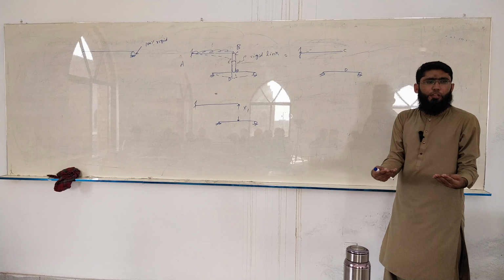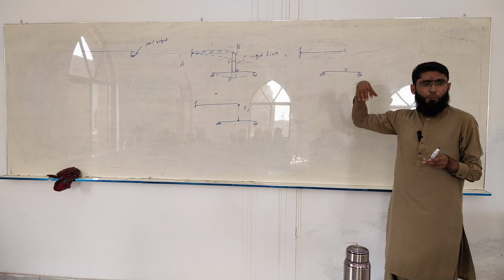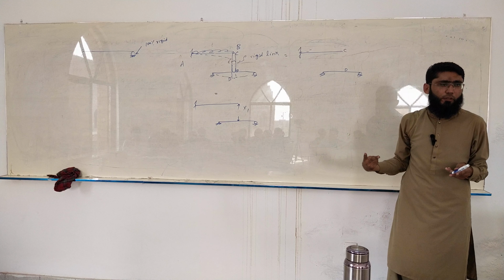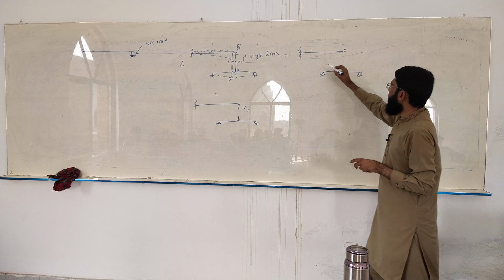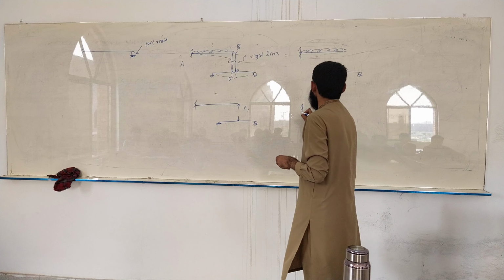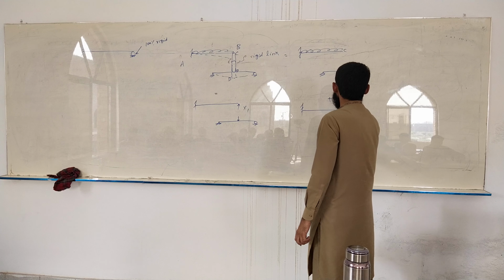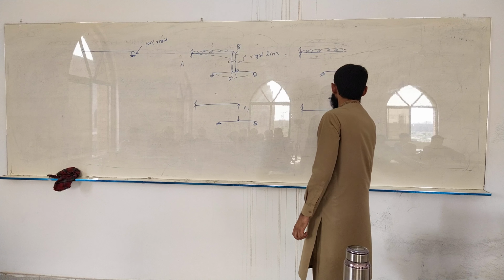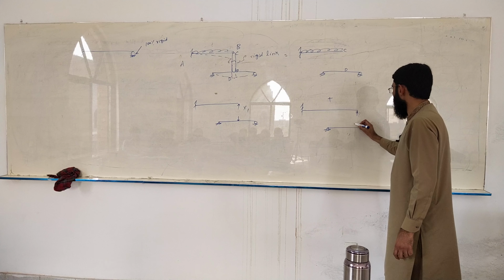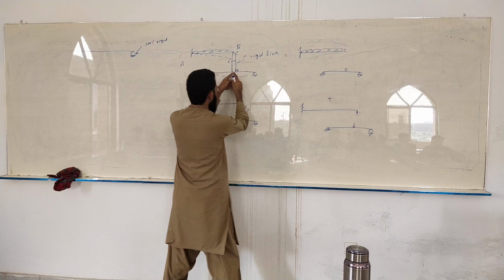Now, just as the basic concept says, you have to consider once the primary structure subjected to the applied loading, and then next you have to consider the unit value of redundant. So in one case you apply this, and then you say, this is at the midspan. This beam, this connection is at the midspan.